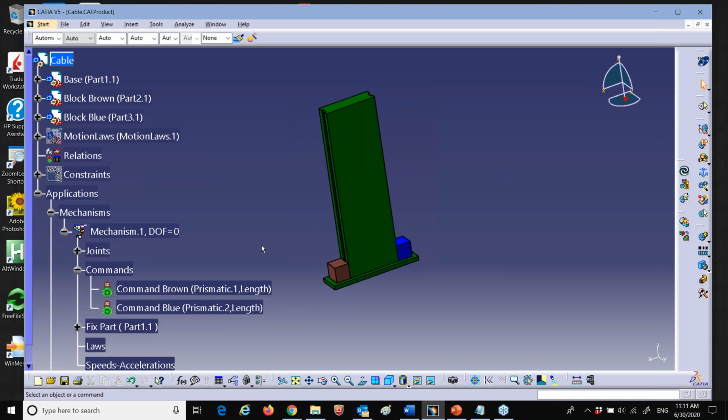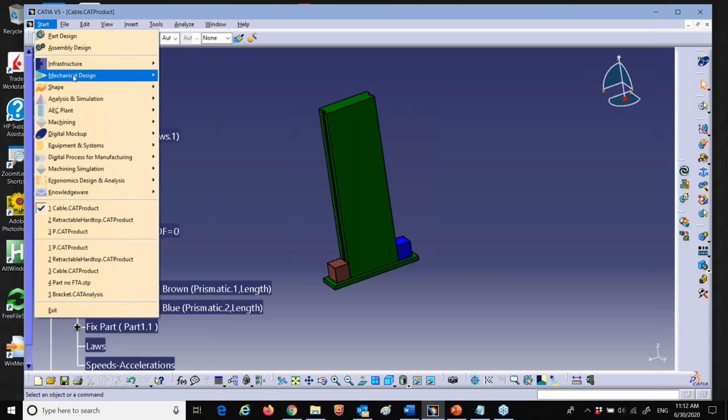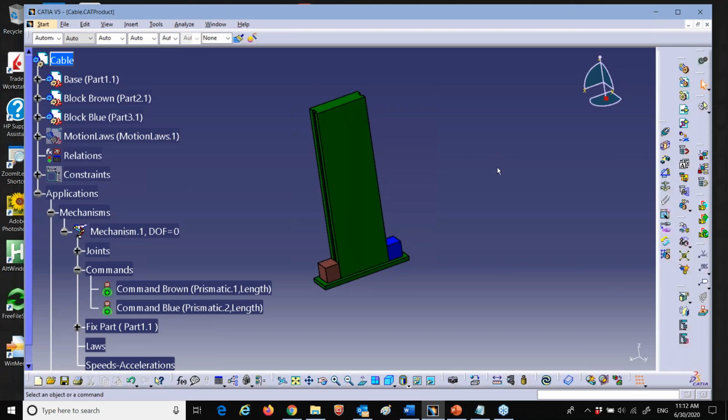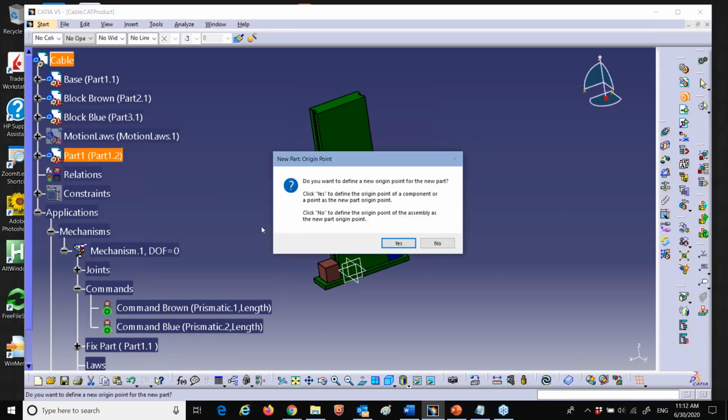Okay, so you got to create 2-dimensional curves. The easiest way is to use a sketch. It doesn't have to be a sketch. Actually, it could be like a 3D curve if you like those, but the easiest option is probably using the sketch. So you start by creating a new part, okay, because the easiest way is to put those laws or curves into a separate part. So I'm going to click create new part. It's going to go here.